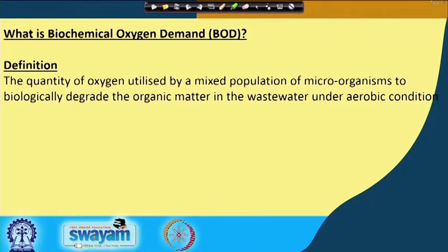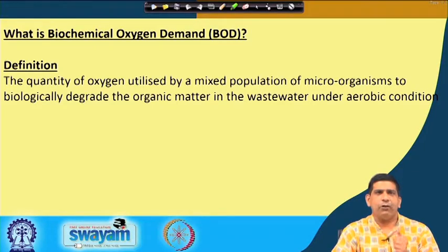One of the major concepts that comes up when we talk about wastewater, when we talk about organic loading on surface water, is the biochemical oxygen demand. It is the BOD. BOD is a very popular concept. If you are looking at any organic loading to any water body, the number one question that gets asked is, okay, what is the BOD number? For example, for any treated sewage or industrial effluent getting discharged to surface water in the country, the BOD number is 30 milligrams per liter. It should not have more than 30 milligrams per liter when it gets disposed into the surface water.